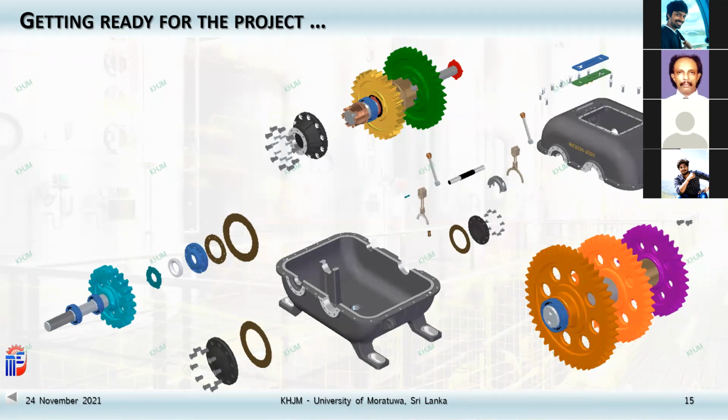All these gear wheels should be able to mount on the shafts, and everything together you should be able to mount on the gearbox housing, and then the gearbox housing you should be able to machine or manufacture, right? And you should have these end caps, seals, bearings, inspection holes. You can see even at the bottom the oil drain if you want to take the oil out, and the shifting lever, the mechanisms, and then the inspection holes, gear shifting, everything needs to be there. Everything needs to be there, right? So if you start in a simple manner, then you can add those things later. Add these things later, right?